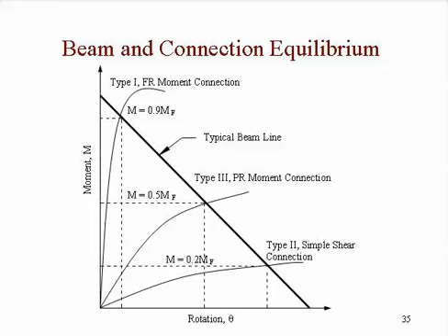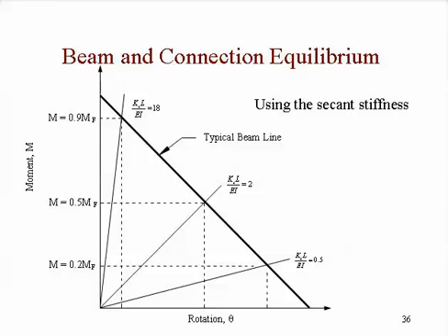And in this case, the graphic that I've used simply shows a moment rotation curve that comes in at 50% of the fixed end moment. And that one we would say, well, that is such that we have to know its actual behavior in order to do anything with it. Down here, though, anything down here, we'd be okay. We call it simple. And anything up here, we'd be okay if we called it rigid. So let's draw those straight lines and see what that means.